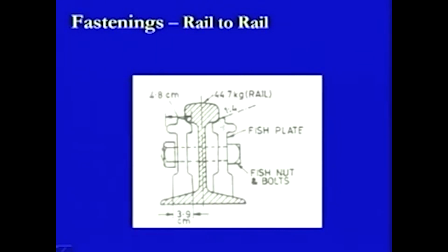Now, as soon as it gets fit in with this rail section here, we can assume that whatever load is coming from the top at this location will get distributed not only through the web section of this rail to the foot of the rail section, but will also get transferred through this section as well as through this section and will come back to the bottom. In that sense, if we assume that there is no load being transferred through the web of the rail, then 50% of the load will get transferred to this one and 50% of the load will get transferred to this one.